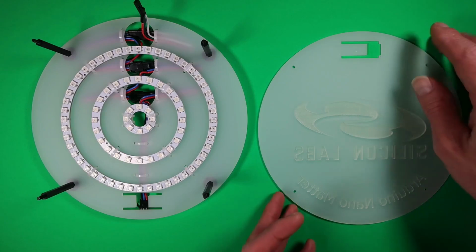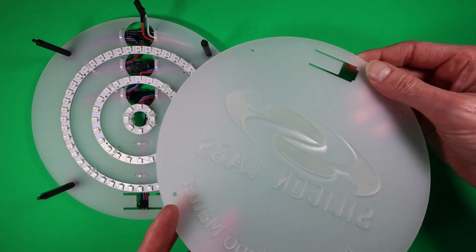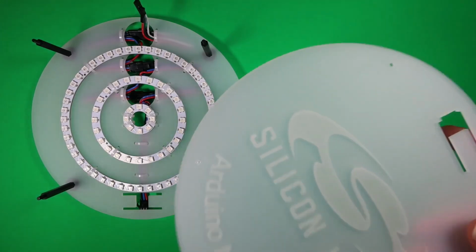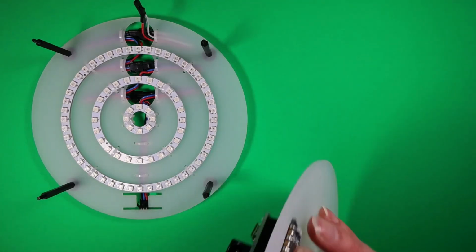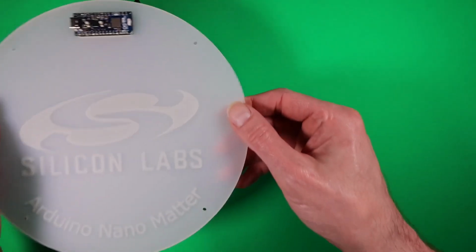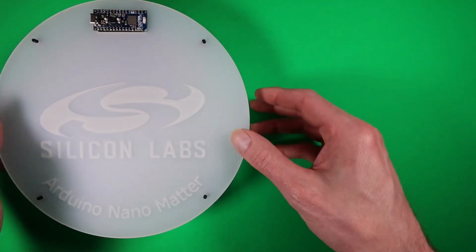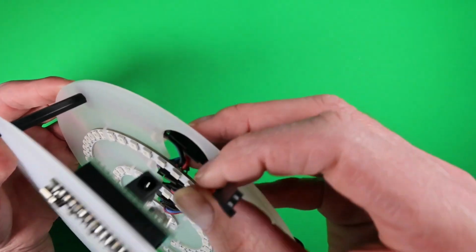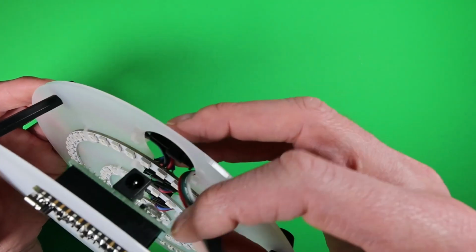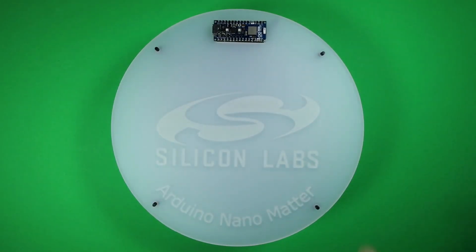On the top panel, the logo and text are etched into the bottom side, leaving a smooth surface on top. The slots allow the nanoboard to be plugged into the PCB to mount it. The M3 nylon standoffs from the bottom panel allow the top to be fixed in place. With the PCB suspended below the top panel, the WS2812 wiring can be connected and power provided via the barrel jack. The nanoboard remains visible with the button accessible.